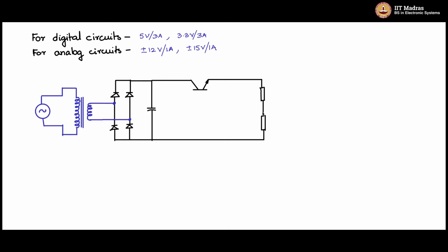It's an attenuator where you tap off the voltage for feeding back at the center point of this. And the BJT here is driven by a gain block K, and there is a comparator which compares the output voltage which is fed back with a reference, V reference.